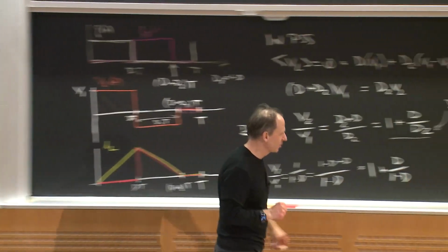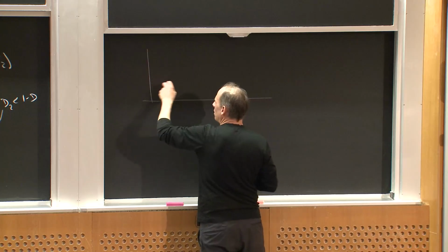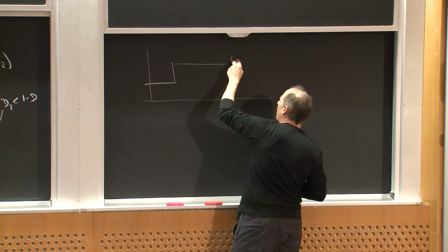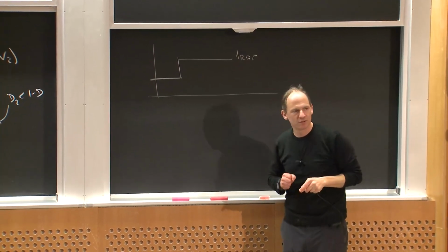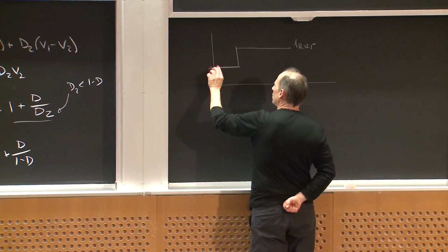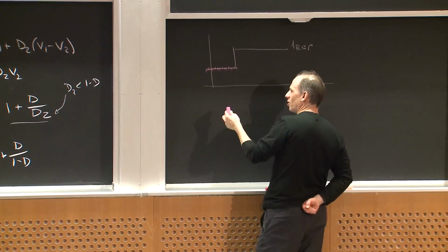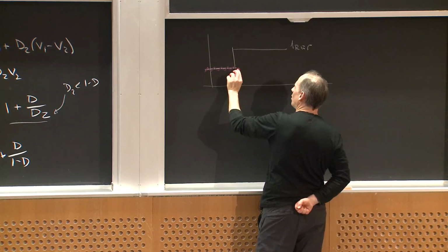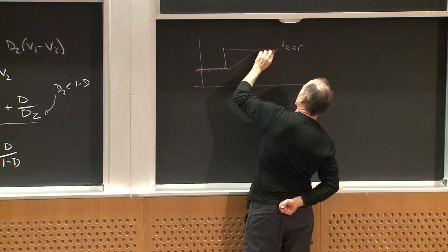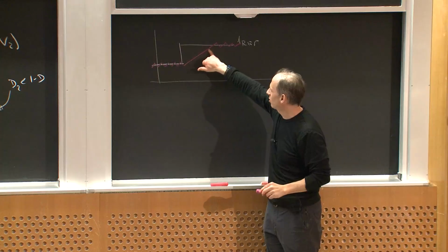Okay? If I have a small ripple converter and I say, ideally speaking, to support the load I had this low current reference and then I stepped it up to this higher current reference. So this is sort of IREF, the reference current for the inductor waveform, right? If I have a small ripple converter, and it's rippling like this, and then I step the reference, I want much more current to deliver more power, what has to happen? Well, the inductor current's going to slew up, and eventually it can get there and I can deliver this again, right? But you notice that there's this time period where the inductor current takes a lot of time to change.